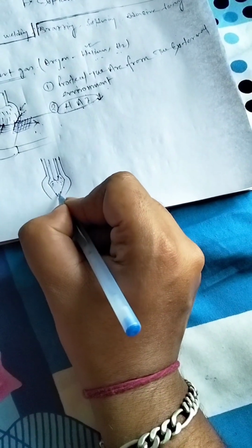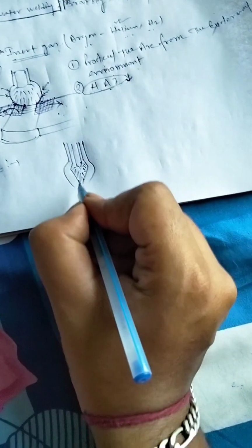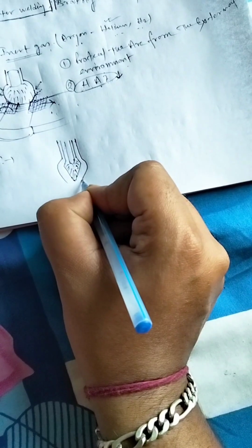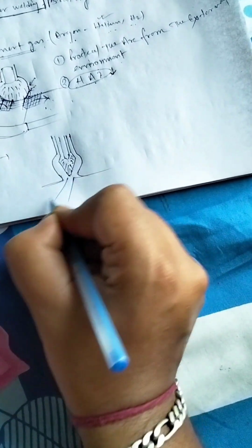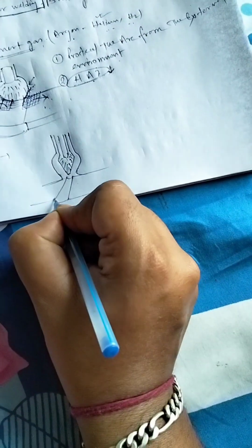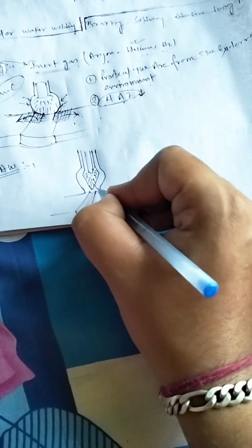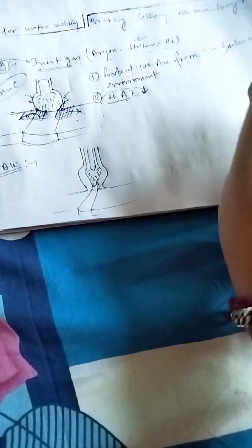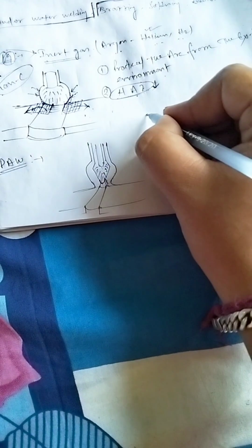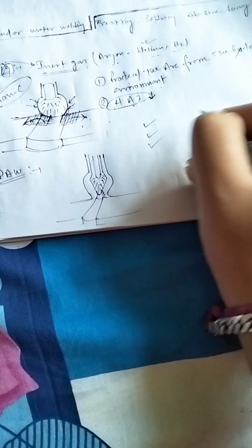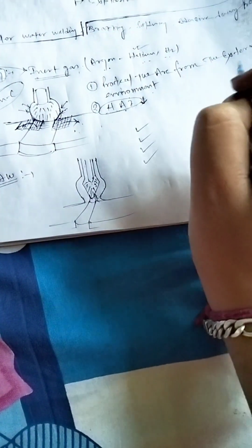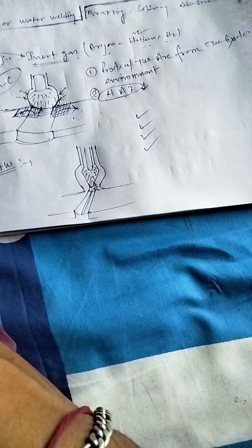The main purpose is the compressed arc. In this diagram you can see the heat affected zone is very localized, and because of that high quality welding is performed. The plasma also acts as a seal, so that gaseous defects are very few. The main advantages are high quality welding, fewer gaseous defects, very high strength, and good corrosion and wear resistance in the welded area.